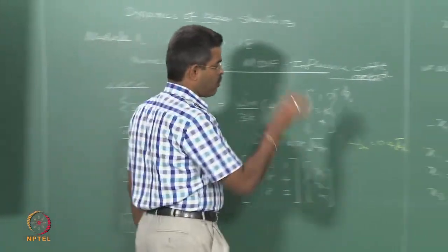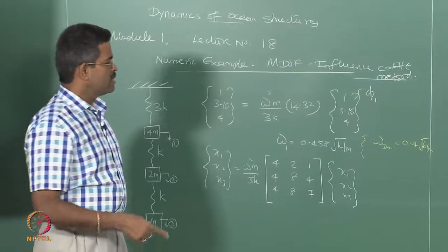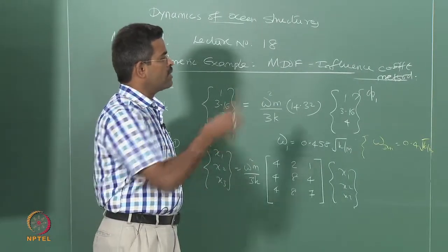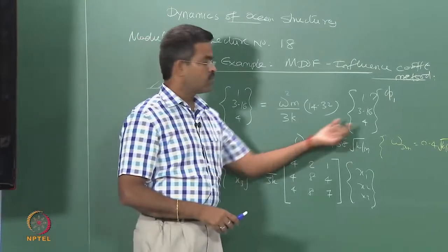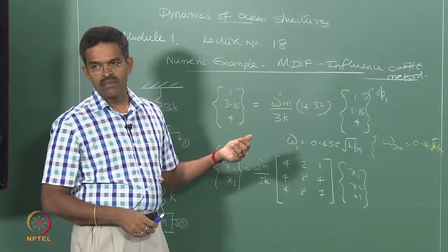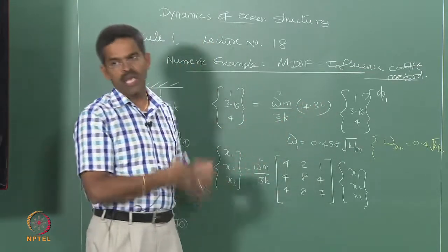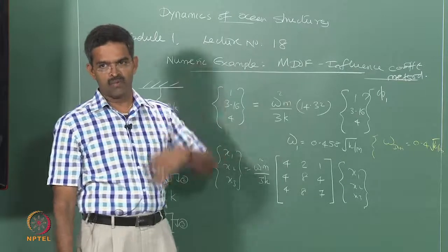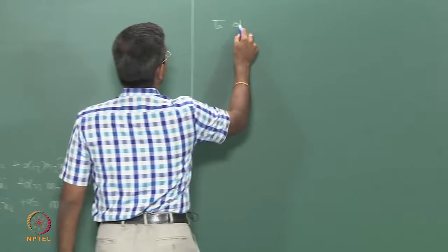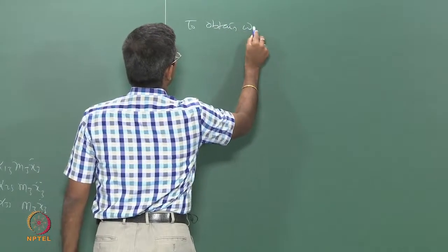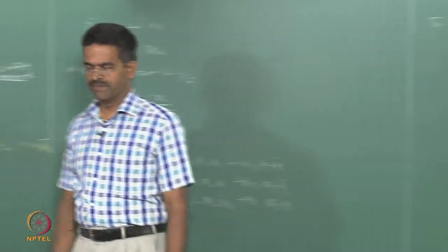Whereas in Dunkerley the focus was on omega and not on phi. So, you must understand the deviation in terms of the algorithm by different methods. Here the focus is not on omega, it is on phi, that is why we are iterating phi. Similarly, since the focus for the entire set is on phi, I am trying to orthogonalize phi first and get the omega 2. Now, to obtain omega 2, phi 2, we know it is a pair, it is a unique combination.